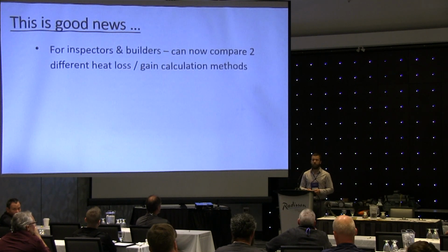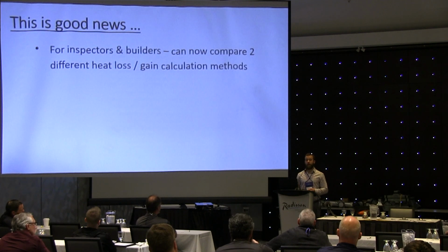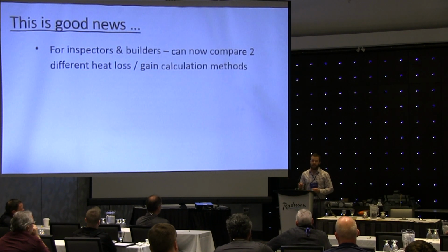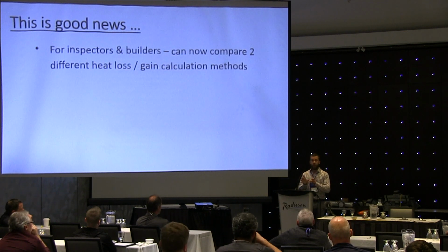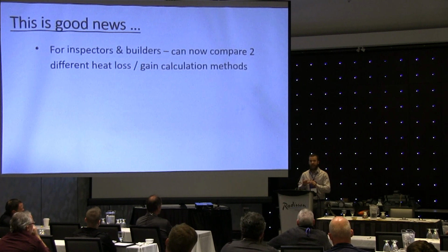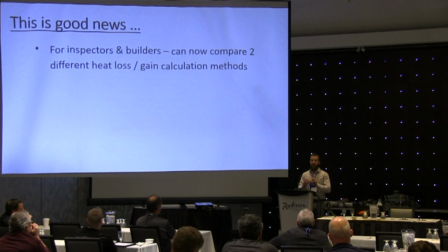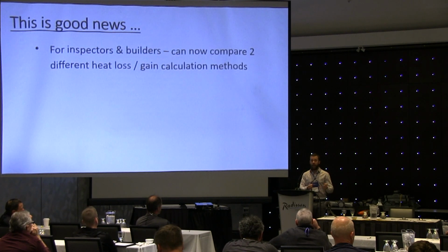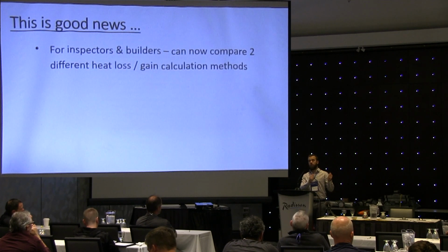Yeah. I would personally tell anyone who's taking my course not to safety factor that way. If you're going to safety factor with one thing, use your indoor temperatures. That's it. That's right in your visible control, and people know that, right? They say, I need to be able to heat this house up to 25 degrees. That's your safety factor there.